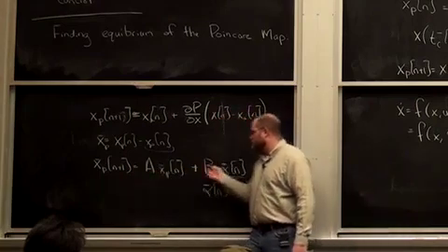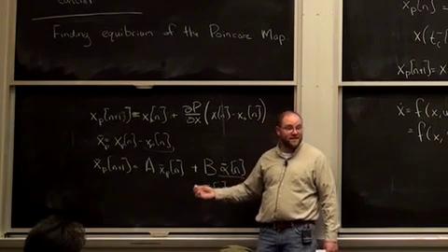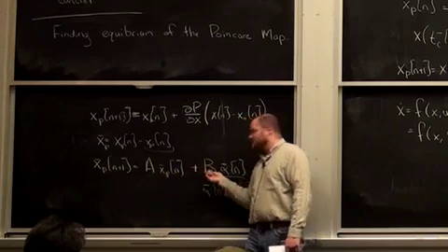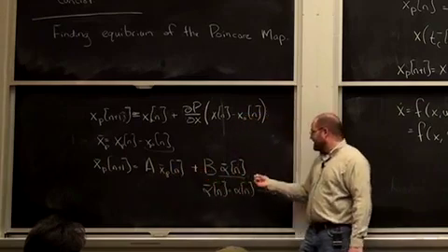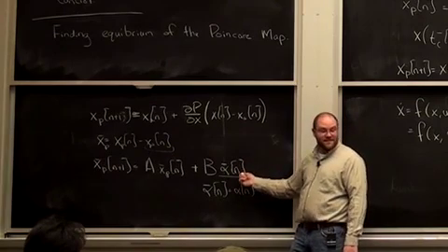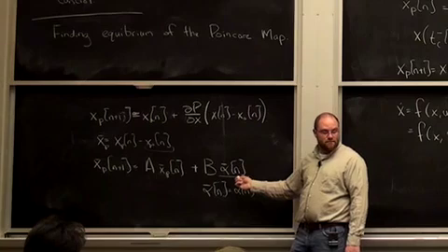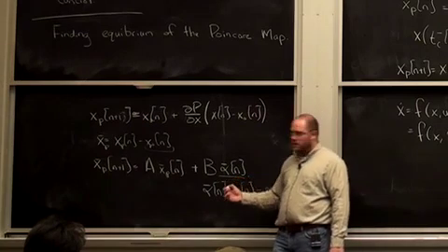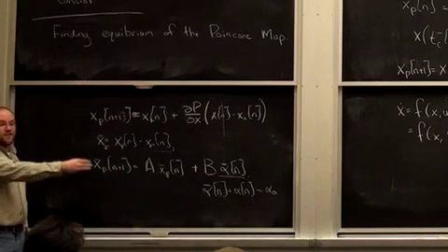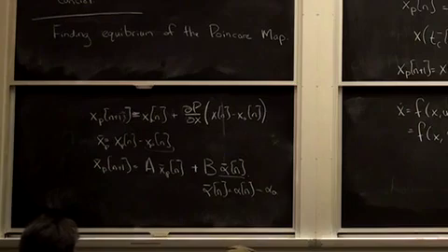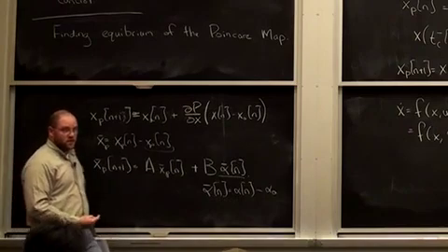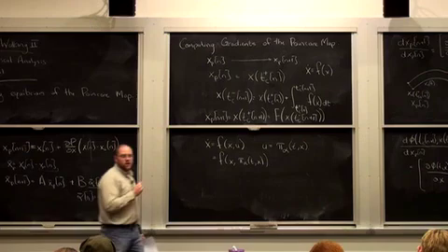This is a discrete time linear system. I could just hand it to MATLAB and call LQR, discrete time LQR. It's DLQR. Give it A, B, Q, and R. It'll give me back a negative K alpha, Kx that defines alpha. You with me on that? So the discrete time summarization of the dynamics in this way can actually make it very natural and very simple to compute controllers which stabilize a walking cycle, for instance, where you make decisions once per step.